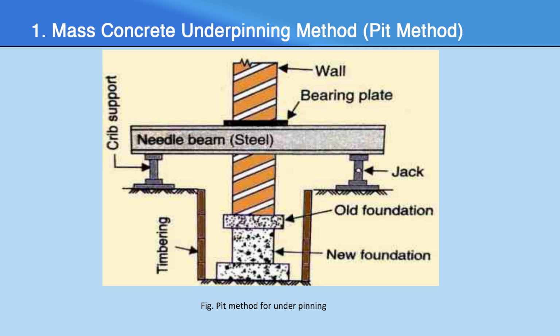When the work of one section is over, work on the next section will be taken up. That is, alternate sections are underpinned in the first round and then the remaining sections are taken up. The figure shows the sections here.